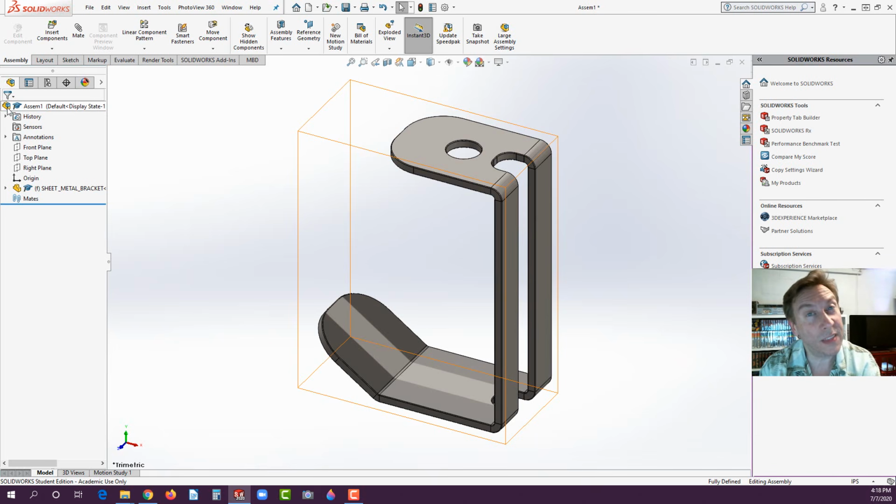That way, every part that they build in the context of the assembly shares the same origin. And if you ever get parts from a company that does that, or designs in that method, you can actually just grab the parts and drop them in by selecting the front plane every time, and it will drop them all in at the origin, and it just assembles itself.